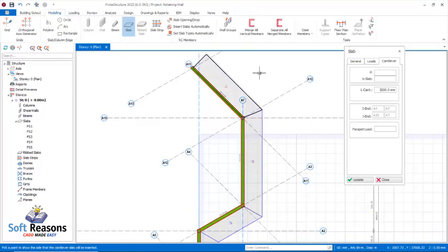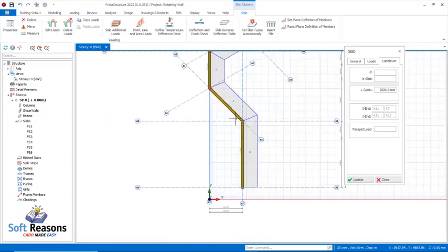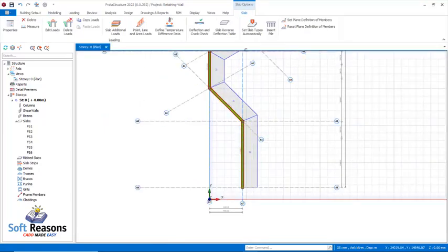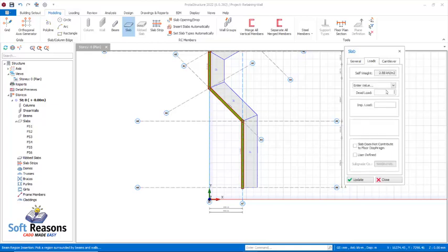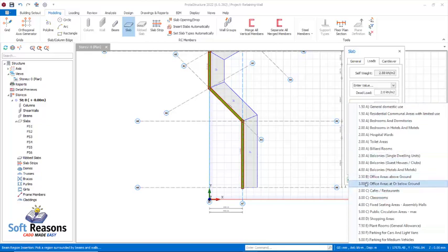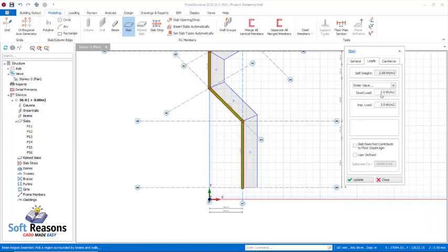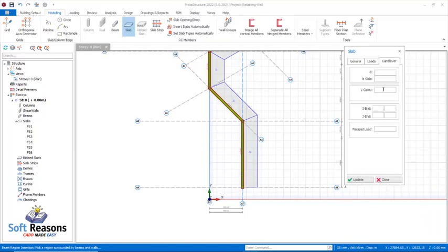All right. Having done with that, coming to this side, you have to close this again, and then navigate to activate the slab again. What we have to do now is we will get to this and select this type of slab 12. Then we get to the loadings. We have here 2 kilonewton, and then in these provisions we have to use this imposed load option. Then come to the cantilever. We have it to be 1 meter.